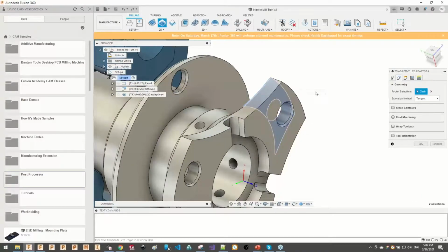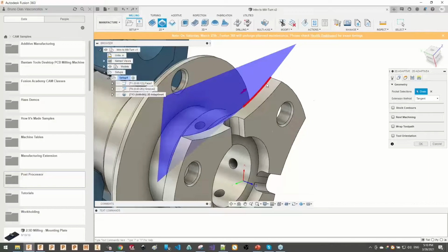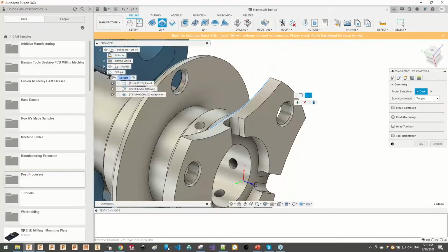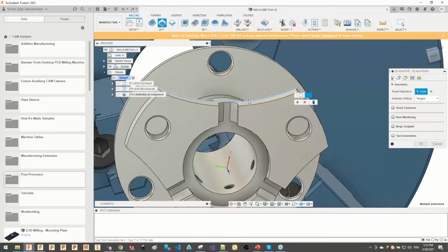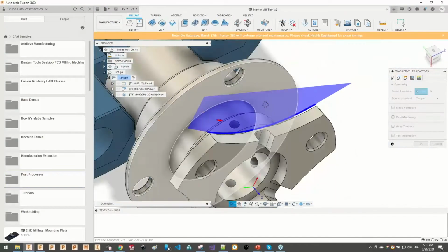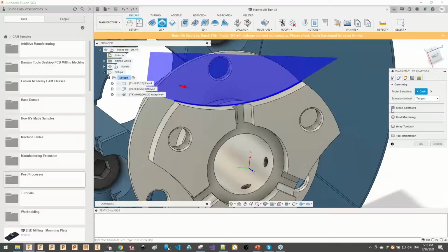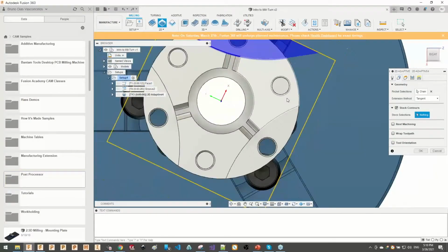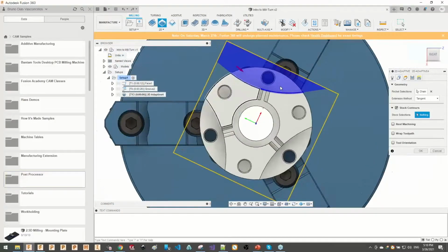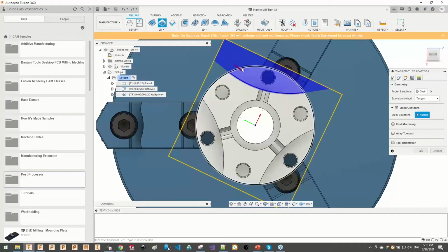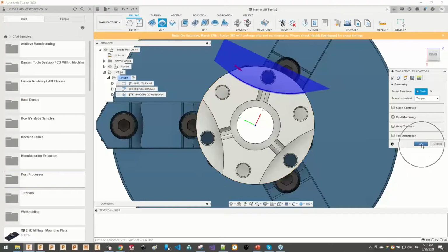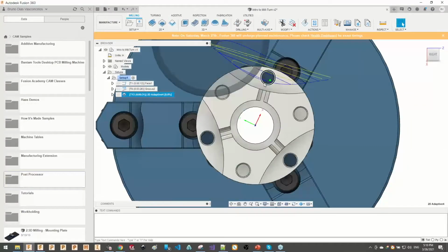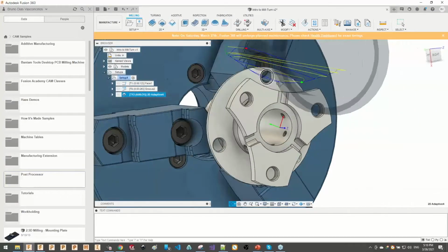Hold on, guys. So click again, and now I want to start propagating my selection. So add those 3 lines, hit accept, and here we go. We got the file, the cut that I'm looking, the slot that I'm looking to cut, or the shape that I'm looking to cut. And if I hit OK, just so you know a little bit, I will get that toolpath created.